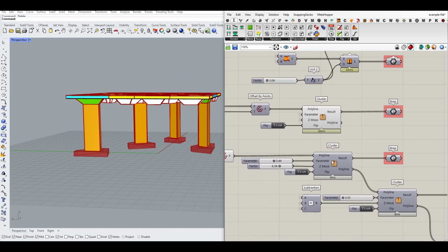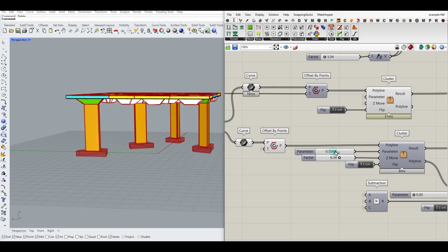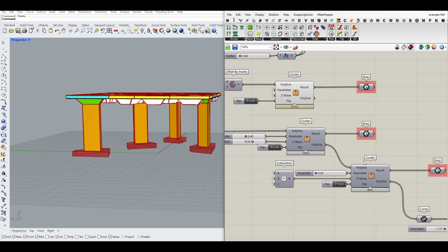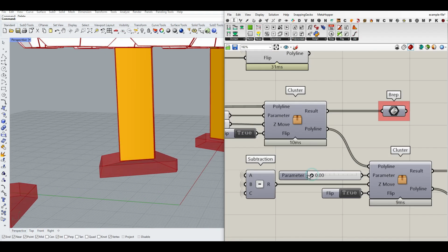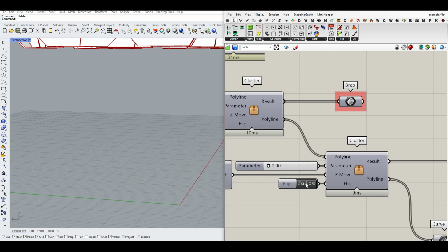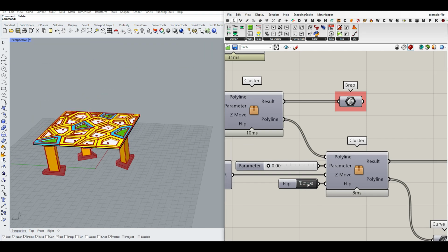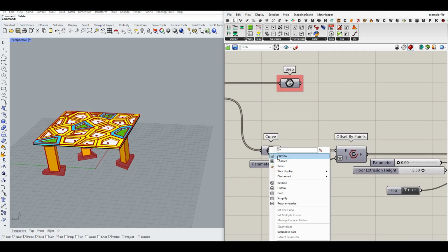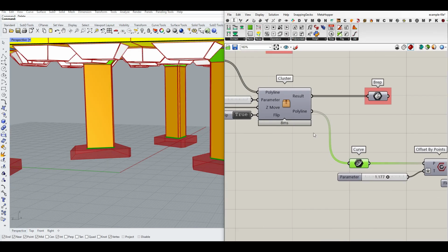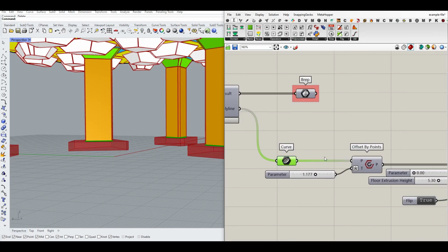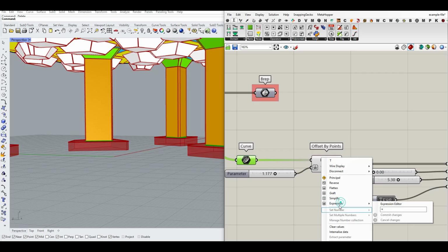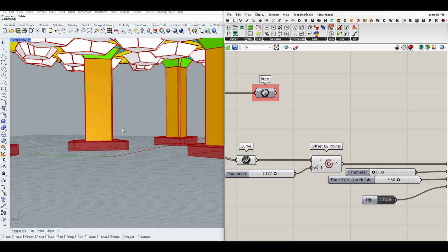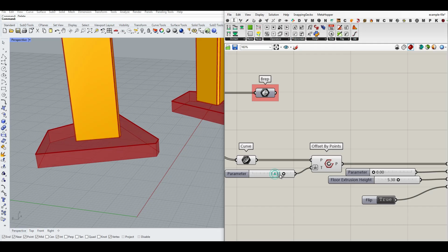After creating this part that we talked about, the second part again is the cluster from the polyline. Obviously, it's the polyline at the bottom. We've used that again to taper that. As you can see here, flipping it's going to go upwards, which we don't want. We brought that polyline from the bottom of the cluster here. We offset that by points. This time I've made an expression minus x to bring it outwards. So you can bring that outwards.